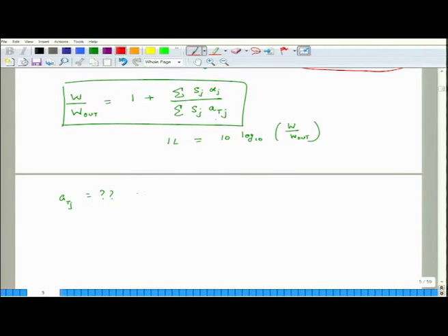Usually, if we are designing the enclosure ourselves, then the transmission coefficient can be calculated by finite element analysis or some other analytical methods. So, we have to calculate it. There is no standard ready-made formula for that. It depends on the size, thickness, shape of the overall panel and things like that.